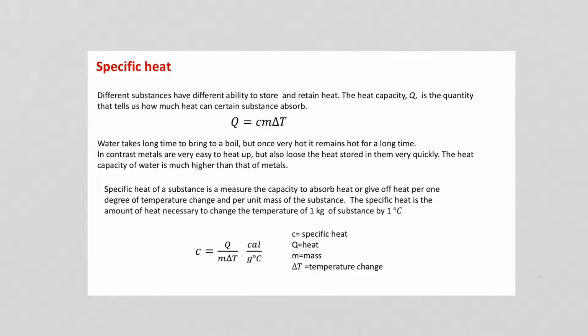The freezing temperature of water is way too high, and the boiling temperature is way too low, because engines get extremely hot, or much hotter than that. But adding ethylene glycol to water expands the range of operation of the mixture, which then makes it suitable to use for heating and cooling of engines.